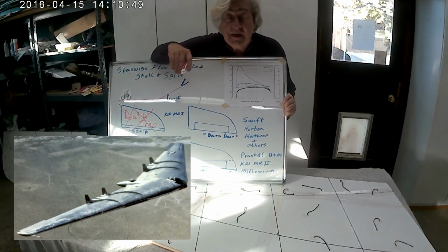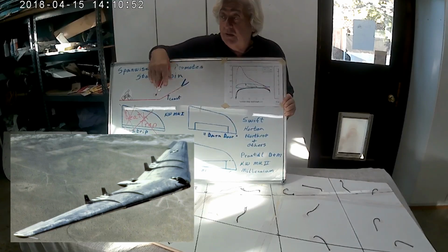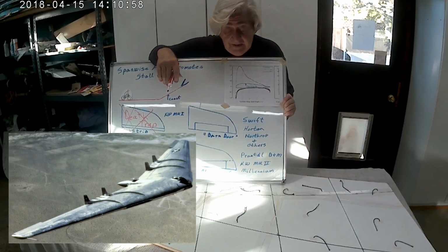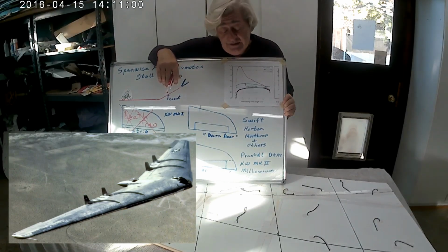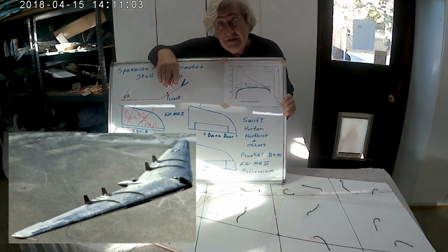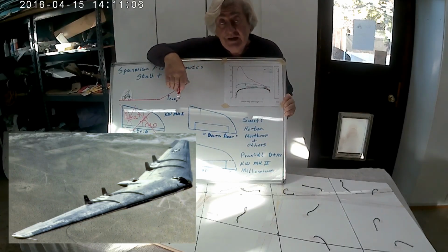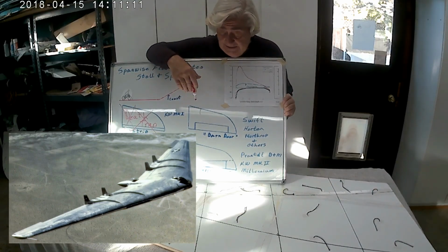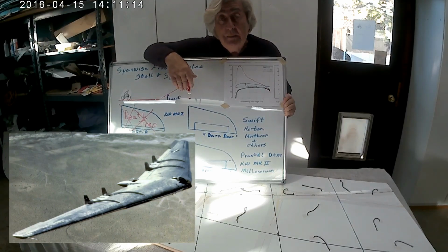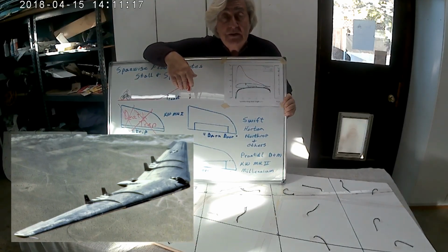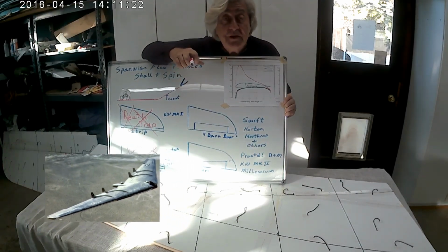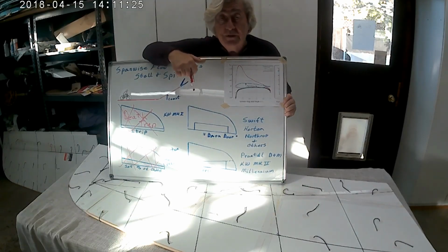You'll hear lots of people say, oh, it was caused by this, it tumbled, that, and the other thing. When the Northrop flying wing went in, they were testing aft CG locations. That's a known fact. And if you're testing aft CG locations and you're flying slow and you deflect your elevon up, well, I think we now understand you could have a problem on your hands. And considering how that thing came apart in flight, it's my guess it was in a spin. They got the nose down, they were recovering from the spin, and they did a pull-up, and that thing was only rated for utility-type loads, 3.5, 4 Gs, something like that, and they just exceeded the G limit and ripped it apart.